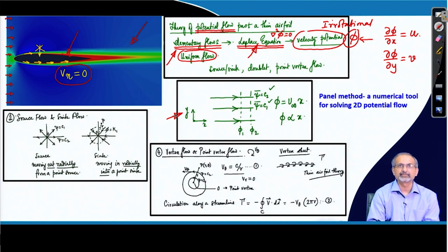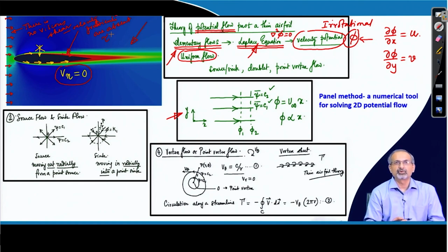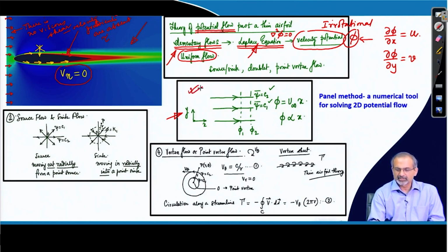The only thing that we are saying is that in such a region there is no viscous shear. That means velocity gradients are absent. Gradients are absent, and therefore, what is the consequence? Tau will be absent, because tau xy is dependent on del u del y, del v del x and so on. So, here tau would be 0. So, it can exist in potential flow, it can as well exist in viscous flow.